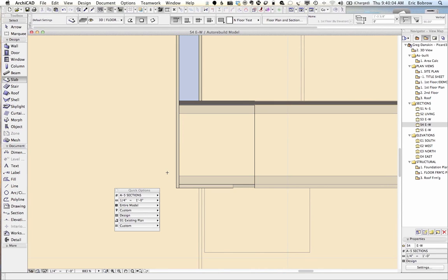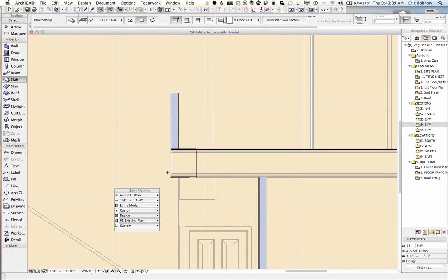So the height, if we're looking at an exterior wall then, and we stretch a first floor wall up to the top of the second floor framing, then the height of that wall is determined by the tallest or highest skin. Yeah, I mean, there are different variations of how you can do it, but essentially you want to make the bottom wall and the top wall meet somewhere along this continuum, and it could be top of core or it could be top of finish. It'll depend upon what you need.